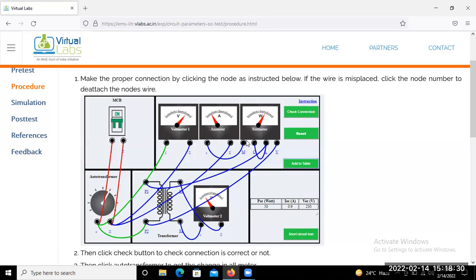Okay, and you will find that L and C are common in the circuit diagram also. So just connect L and C with one wire, and that will short circuit L and C. From the L point of the wattmeter, it goes to the positive of the LV winding, that means here. And from the V terminal of this wattmeter it goes to the negative of the LV winding, and again from this point go back to the auto transformer.